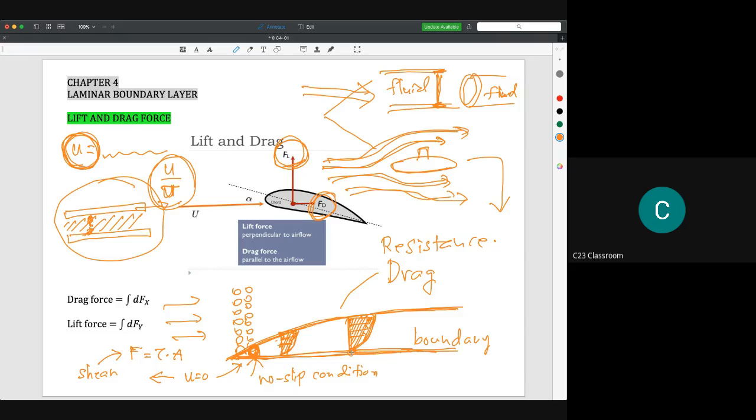If it is irrotational flow, meaning zeta is equal to 0, you can continue your calculation with ideal flow theory. But if you determine that zeta is equal to certain numbers, it means it is a rotational flow, which means your flow now will have a boundary layer. You may refer to the previous notes where I explained rotational and irrotational flow.